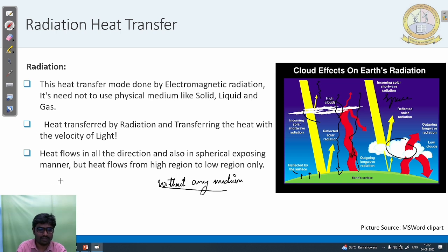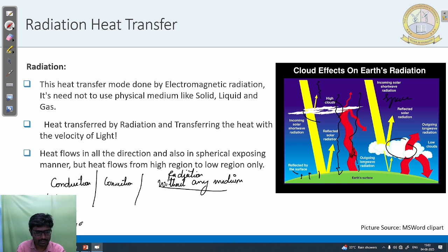Okay, so I can see three things: one is conduction, the second thing we have seen is convection, and the third thing is radiation. If I give some tabulation, we can easily say what each is. Conduction happens between molecules, but only in a single medium. That is very important. Examples we have seen include a metal rod heating or cooling.